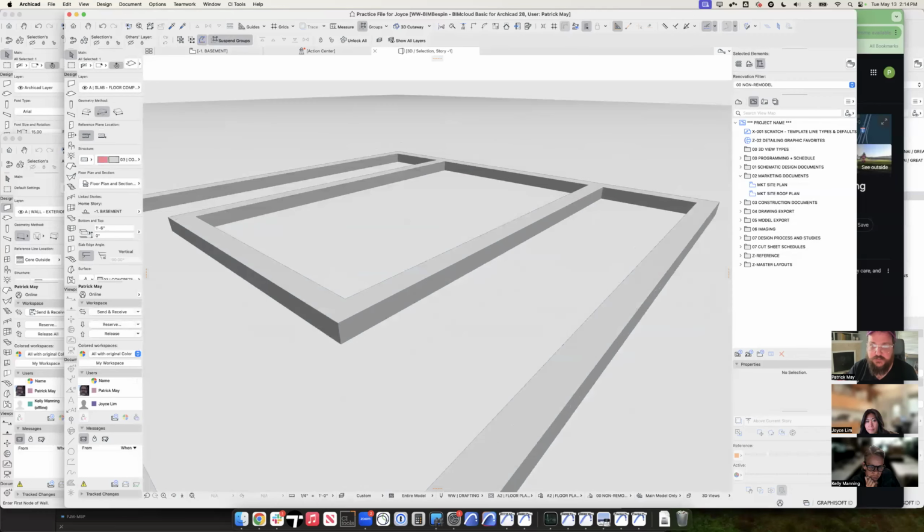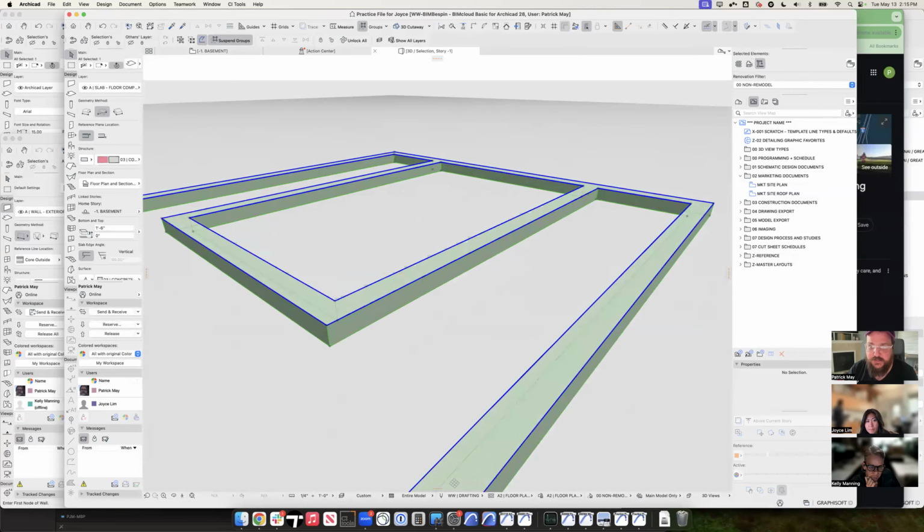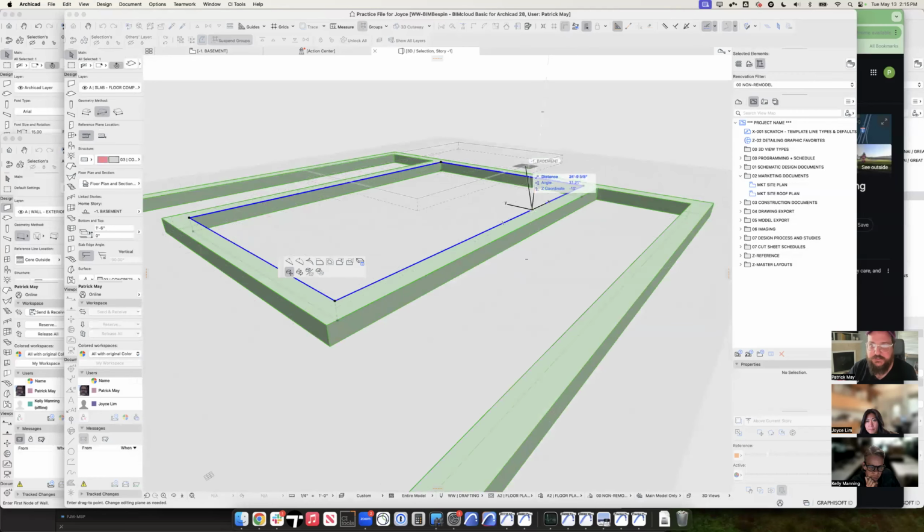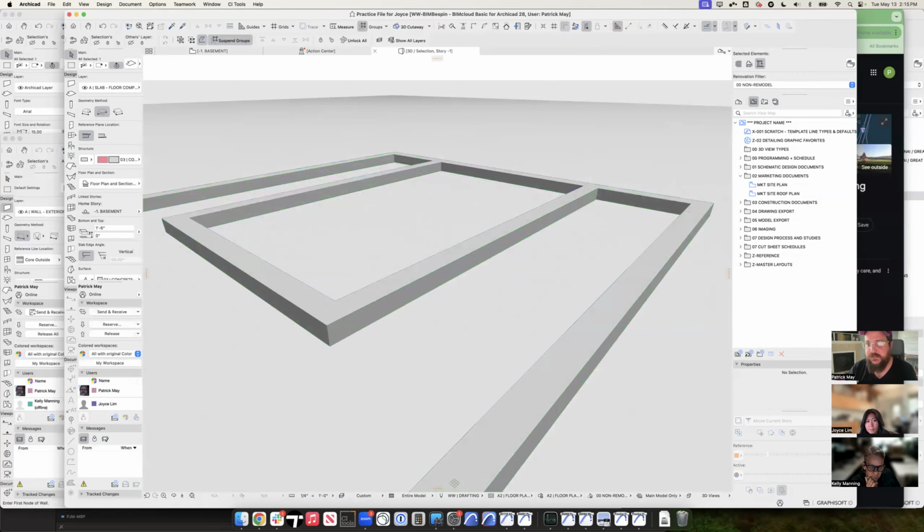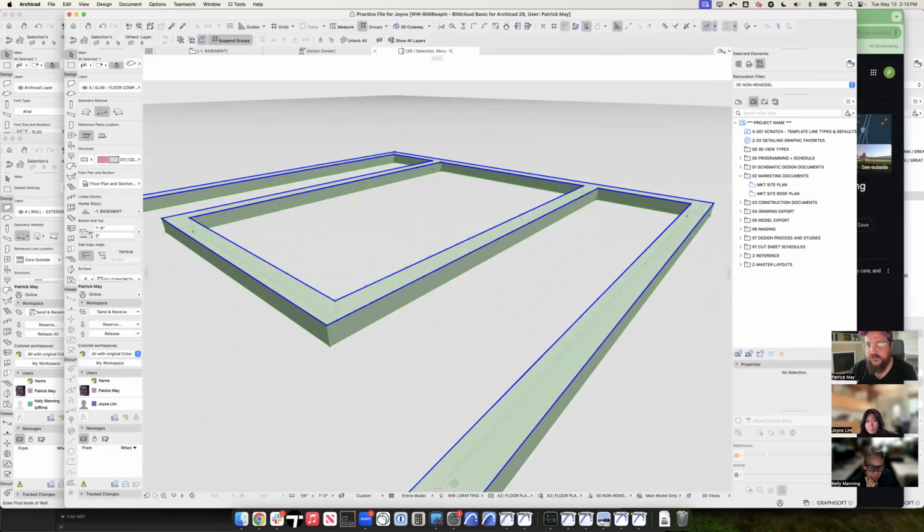Looks okay, but we can even take it a step further. We can say that maybe this inner edge here in 3D, I'm gonna isolate that out. So select the slab, select that geometry. Notice the blue line is only around that inner edge. And I can say that maybe this has a custom edge. On the Info Palette, I'm gonna click right there and say selected polygon has a custom angle of, I don't know, 85, or let's make it like 60 degrees, right? So now I get that slab that's tapering in like it would be on a turn down.